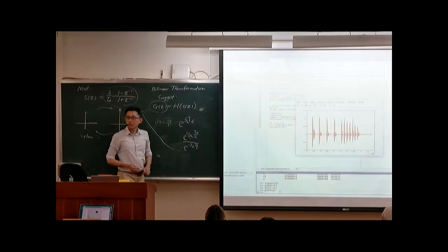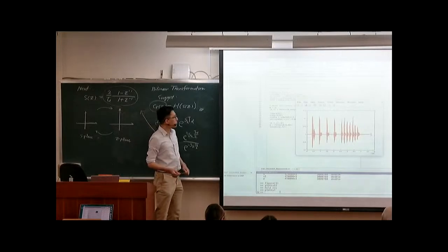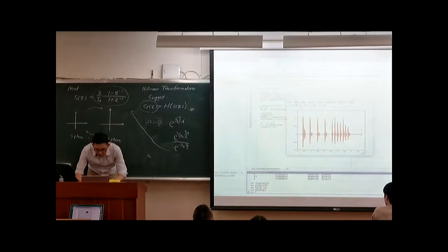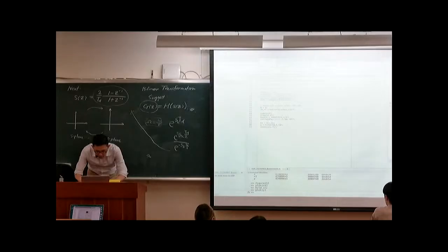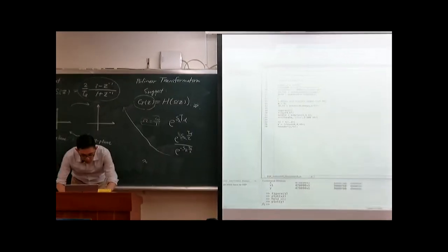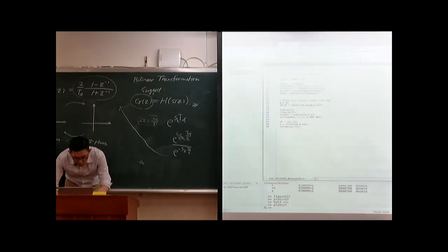Doesn't change that much. Okay, it does not change that much. But I can try to lower the cutoff frequency right here. Let's say it's pi over 3. Let's reduce it to pi over 12. Okay, and also let's increase the Butterworth filter order to, let's say, 10th order.